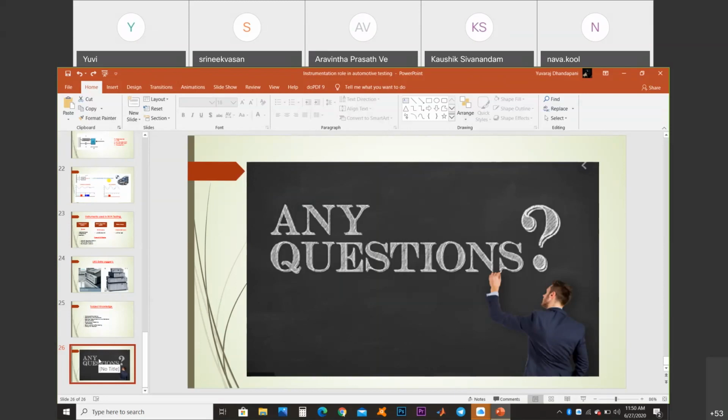Once the raw data is collected, we have to move the data to data analysis software to find out your requirement, to make sure what your requirement is. Say, for example, if you want to find out what frequencies are present in it, we need to go for FFT analysis to find out what frequencies are acting there. As I told you, we are going to measure the vibration in the injector, right? But whatever data you collected is a combination of all the signals. In an engine, you have many vibrations, so whatever data you collected is a combination of many signals.